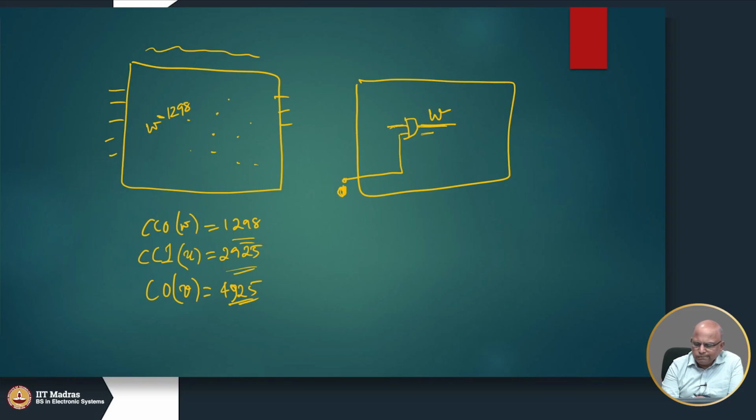Okay. Similarly, if I have a wire which is very difficult to control to 1, I can always put an OR gate here. If this is 0, no change, the original circuit remains as it is.